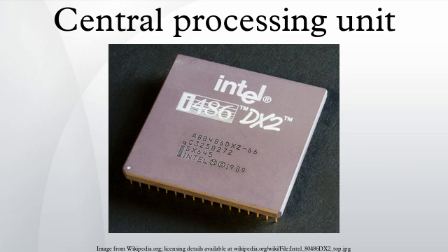By the early 2000s, CPU designers were thwarted from achieving higher performance from ILP techniques due to the growing disparity between CPU operating frequencies and main memory operating frequencies, as well as escalating CPU power dissipation owing to more esoteric ILP techniques. CPU designers then borrowed ideas from commercial computing markets such as transaction processing, where the aggregate performance of multiple programs, also known as throughput computing, was more important than the performance of a single thread or program.